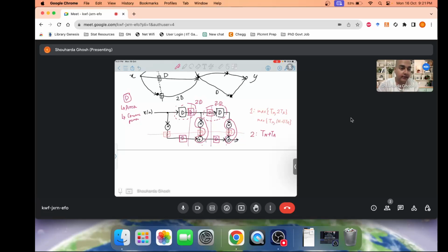In reality, if you study static timing analysis, these registers have something called the setup time and hold time. Why are they important? Because you cannot arbitrarily give a clock signal and expect data to be latched into the register at any point of time.